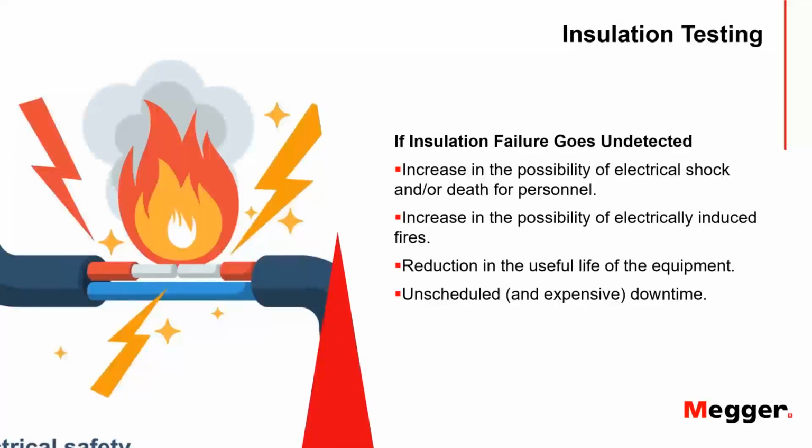These are the main problems that you're trying to avoid with having good insulation and insulation testing. Of course, the main one would be electric shock. Insulation breaks down, you get a voltage gradient across a metal frame of a piece of equipment, and you do not want to become the path to ground. There's also a lot of fires that are induced in this manner. Don't rely on your circuit breakers to protect you. Yes, they do, but not in every single instance.